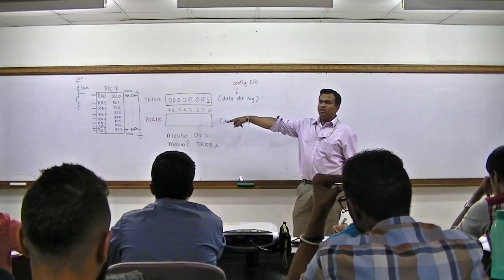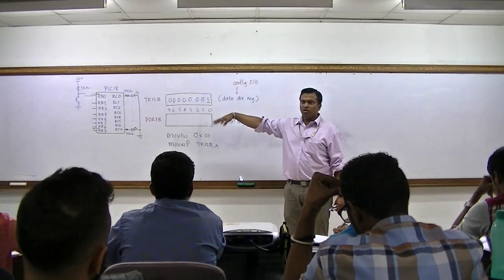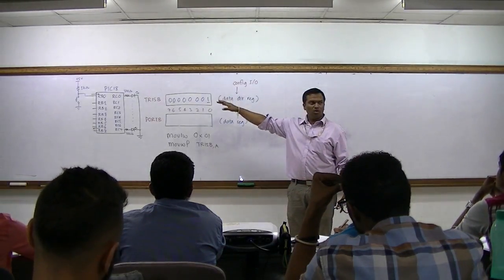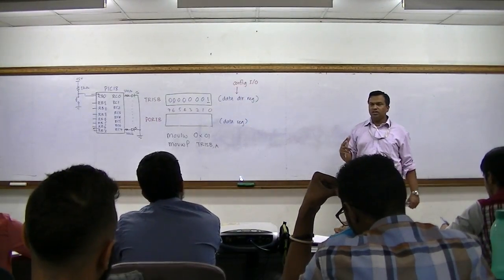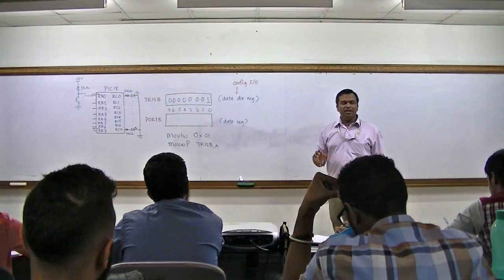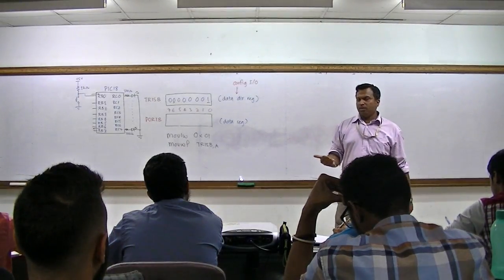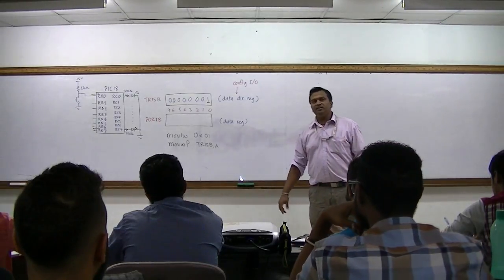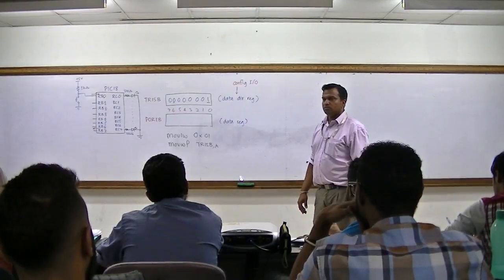So in port B we have one input. In port C we have, after the dot, the LED connected to all the pins. Then we have 8 LEDs. Since now you have 2 ports, just remember that in input/output the first thing you do is configure. So for port B, do you want to configure it as input or output? Input.